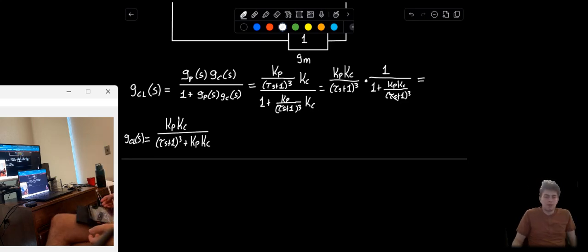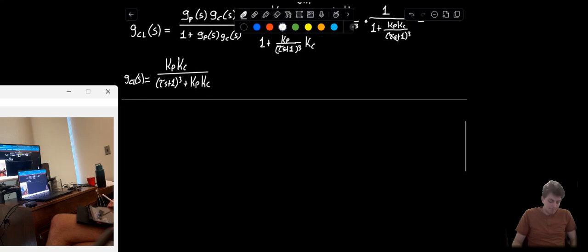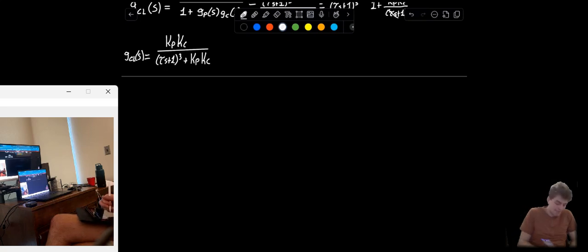Basically, if the terms in the first column of that matrix are positive for our transfer function here, then we can say with certainty that our system is stable. So, as we'll find, that notion will put limits on our controller gain value. So let's go ahead and try this here.